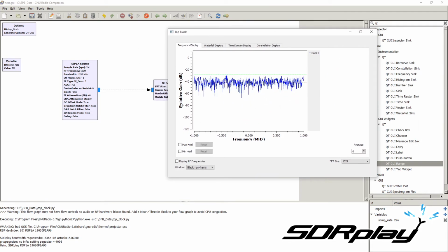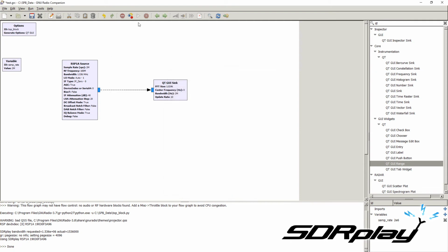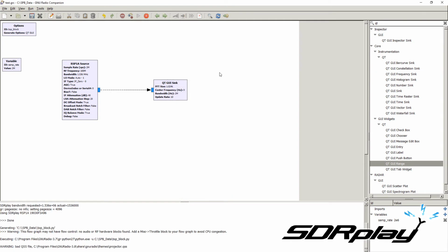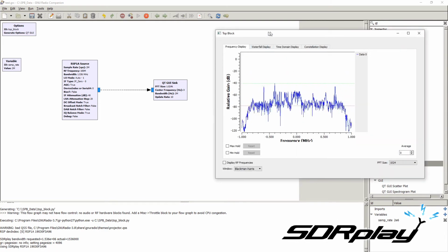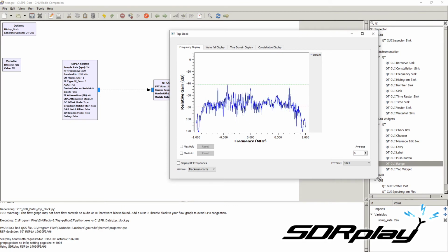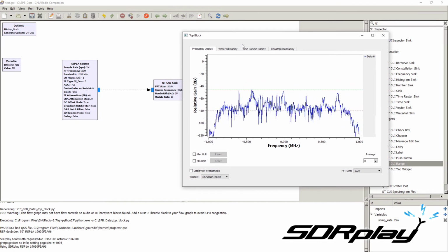The signal is too powerful. To reduce the power, we can increase the LNA attenuation step, which reduces the power coming from the LNA. We can type, for example, something like 20 dB. Press play, and then we get the radio stations. This happens if the signal is too powerful, because it will overload the SDR. Now we see the signals.